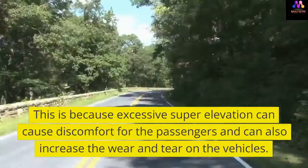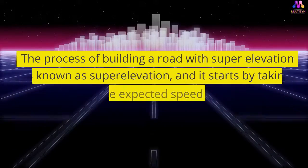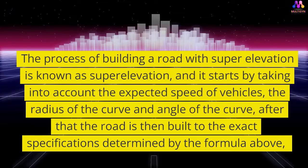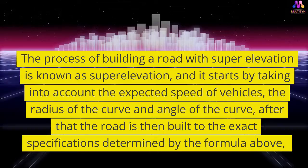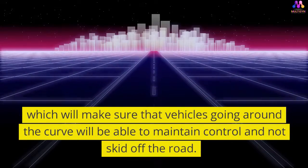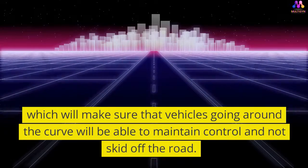on the vehicles. The process of building a road with superelevation is known as superelevation, and it starts by taking into account the expected speed of vehicles, the radius of the curve and angle of the curve. After that, the road is then built to the exact specifications determined by the formula above, which will make sure that vehicles going around the curve will be able to maintain control and not skid off the road.